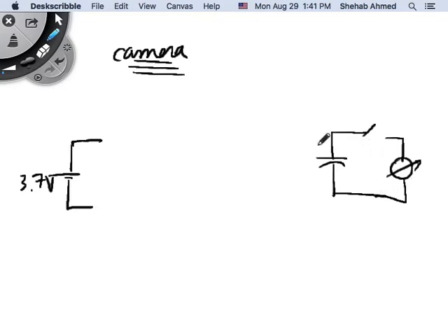What happens is you typically charge a capacitor up to 400 or 300 volts, and then, remember your transient response stuff that you did in 214, you close the switch. After you close the switch, all the energy stored in the capacitor will be placed across this flash, and you get a lot of energy instantaneously on this light bulb, and it glows.